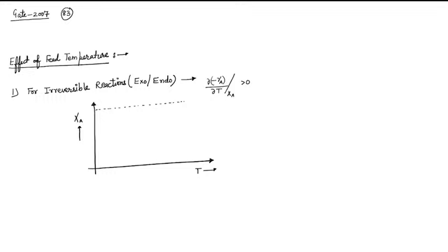Good, Devesh. So that will be in this way. Correct. This thing we already saw in one of the questions. So minus RA, let's say the value is 1, 2 or any value for this rate, because that is the concept of contour. I told you that to draw the 3D curve in 2 dimensions, we take one of the variables as a parameter, meaning across this curve rate is constant. We want to draw conversion versus temperature, because rate is what?